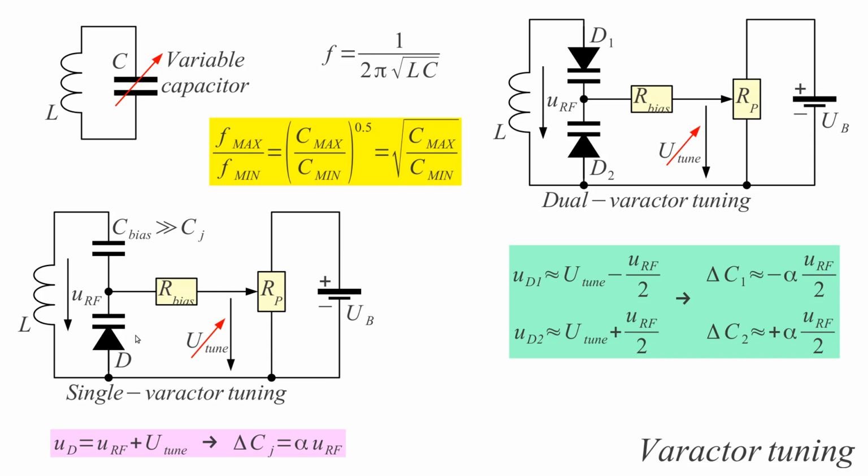Okay, there are varactors especially designed to produce harmonics of the signal. So this is another application of varactors, to produce harmonics. But if we don't want harmonics, then a very good trick is to connect two varactors in series, and this is actually anti-series, so that we apply the same DC bias to both varactors, and we apply the RF voltage to one varactor with the reverse polarity of the other varactor.